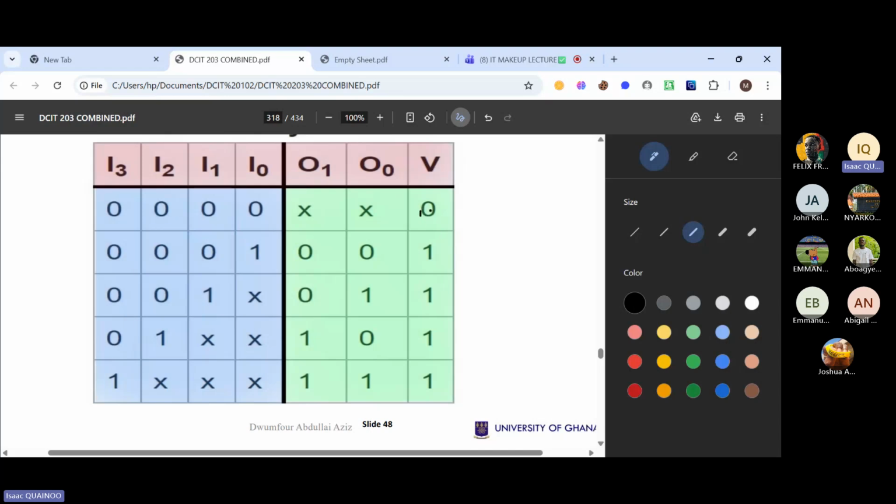If we assign a priority of 0 to that particular circuit, then it works in a similar manner to our enable, so all our inputs here become don't care, and directly everything goes down. If you assign a priority of 1, everything works as it's supposed to.